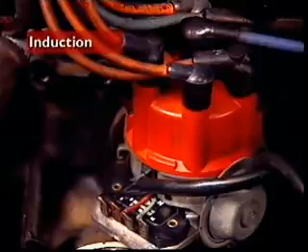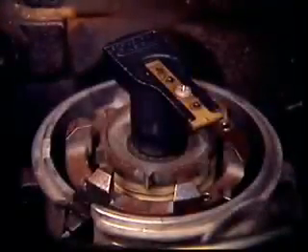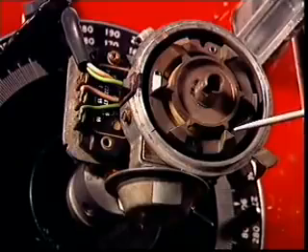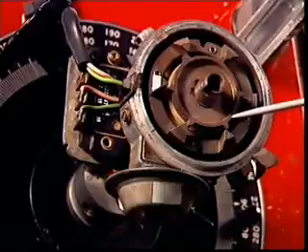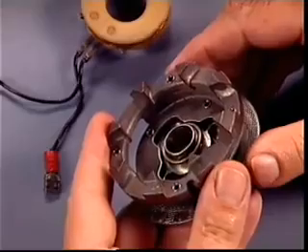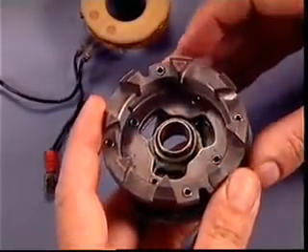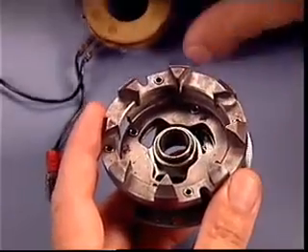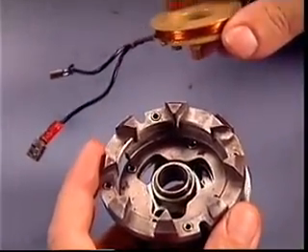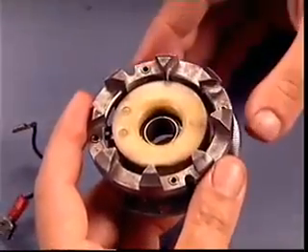In electronic ignition systems, the contact breaker is eliminated and the switching or triggering of the primary circuit is carried out electronically. In induction type systems, a pulse generator has a stator mounted on the distributor body and a rotor unit called a reluctor attached to the distributor shaft. The stator has a circular permanent magnet with a number of projections or teeth corresponding to the number of engine cylinders, and a stationary coil of fine enameled copper wire wound on a plastic reel and positioned inside the magnet.